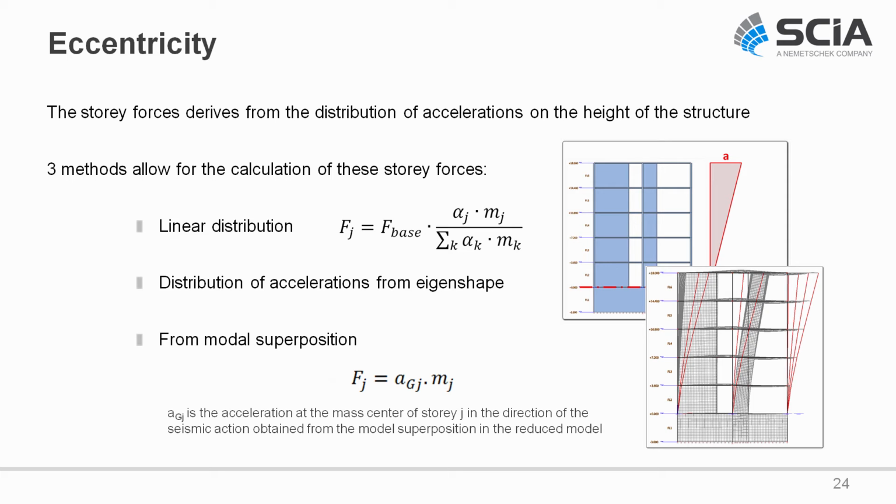This approach is not described in the Eurocode. It is more conservative than the other approaches, as it uses an envelope of accelerations instead of a distribution of the resultant base shear force. However, it has the advantage of covering cases where higher order modes cannot be neglected for accidental eccentricity. In SCIA Engineer, we have to activate the IRS model in order to add the accidental eccentricity.